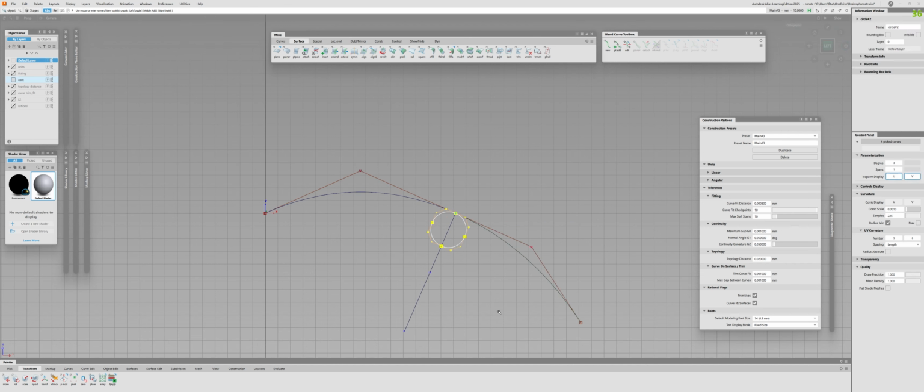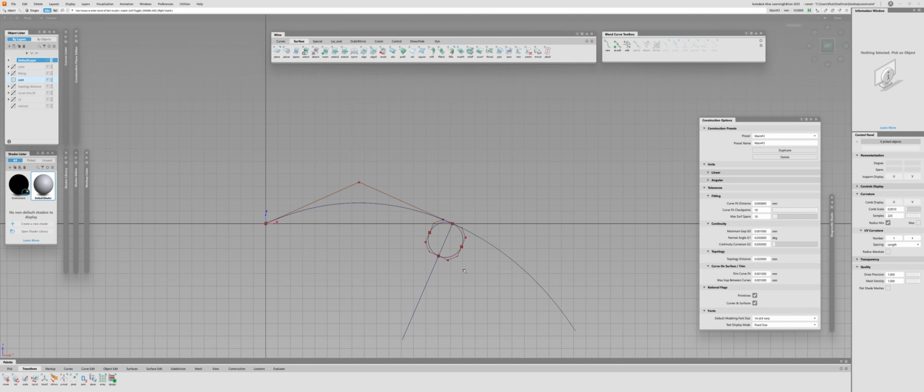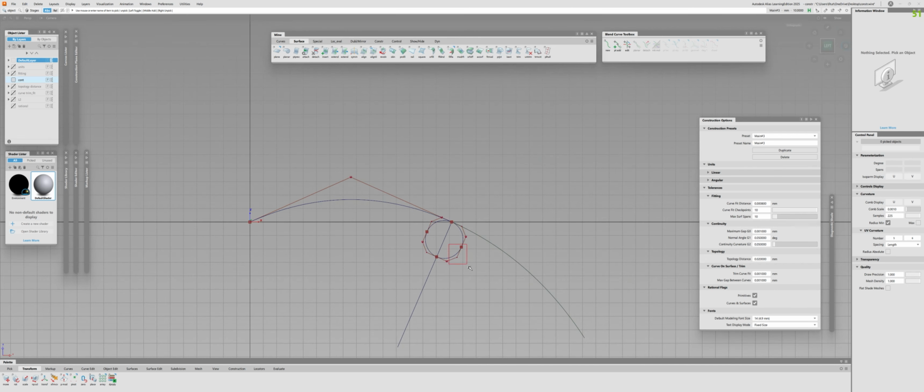Once again, if you want to know the details and learn about the deviation and how it operates, and what is reciprocal for these radiuses, just go check that video. Once again, it's somewhere here, I believe, or in the description. But basically, eventually, it will get some value. And this value is not a degree. It's actually a linear measurement, so a linear value. And then it uses this as the tolerance, and you see it in your tolerance. So this 0.05 is a linear value, the difference between the two circles, which describes the curves, and that's how it basically calculates the curvature.